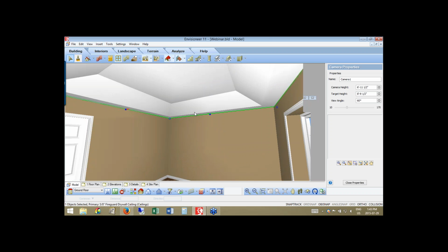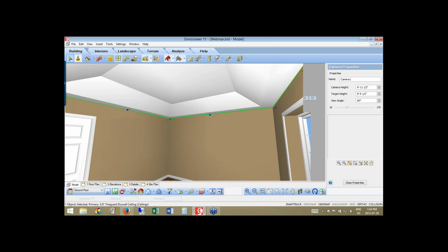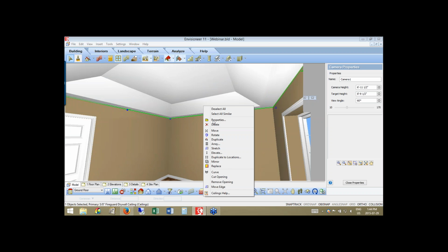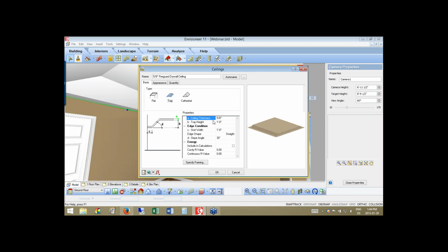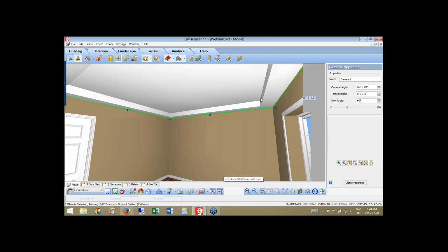Okay. The only difficulty that you have in selecting the ceiling in this view is if you want to change the sides, it's kind of difficult to see those arrows. So I can select those arrows, but it is kind of hard to see them. But I still can do it. It's just a little bit more work to see them. So if I wanted to make a change, I could select those arrows here, even in a 3D view, and look at their properties. Perhaps when I see it as a tray with that full 1 foot going up 30 degrees, maybe I want to change it to 90, and maybe I only want to go up 6 inches so that I can change that and see that coming over a foot, going up 6 inches, and a straight 90 if I prefer that look instead.